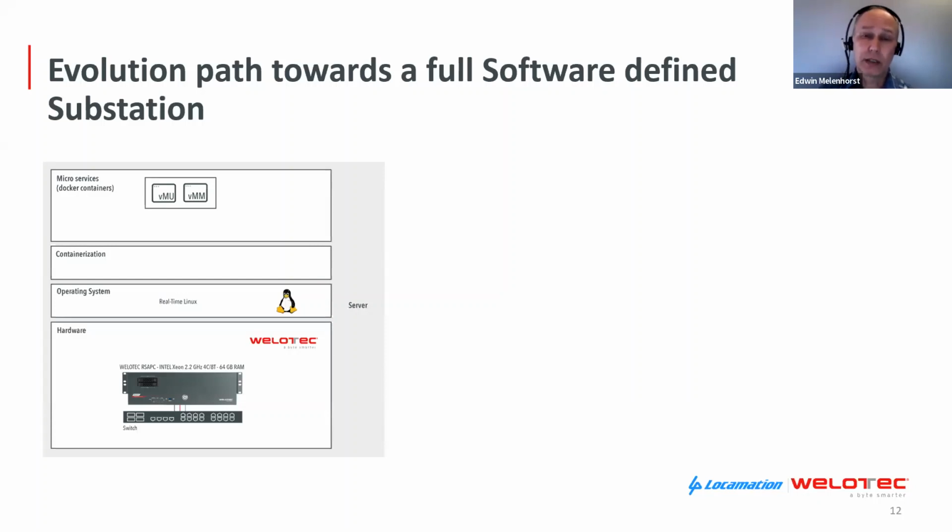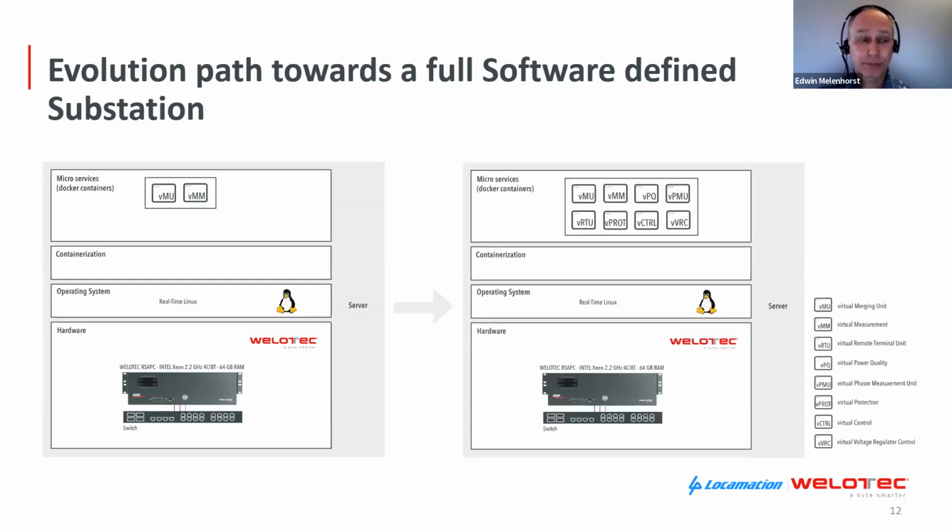And combining the VMU platform with third-party IEDs is also possible, as everything will be based on standardized IEC 61850 communications like sampled values, GOOSE, and client-server communication. Okay, can you show the second picture?